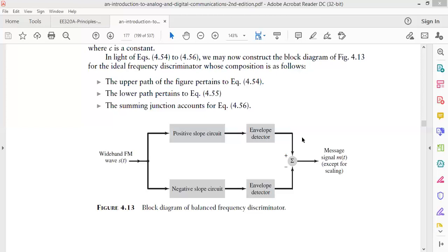On the other hand, at the demodulator circuitry, high frequency attenuation, and high frequency boost up at the modulator portion. High frequency attenuation at the demodulator section to obtain the low frequency message is called the de-emphasis procedure. So these are the most important blocks that I need for boosting up the modulated signal or getting the message signal back.